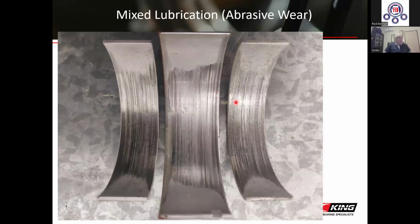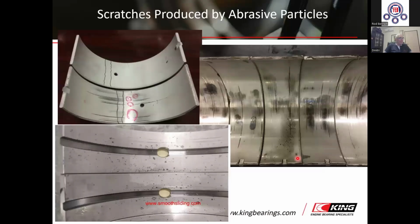Another example of bearing affected with a heavy abrasive wear you can see in this image. In this slide, you see bearings affected with abrasive particles circulating in oil. Scratches on the bearing surfaces can be observed here and here.